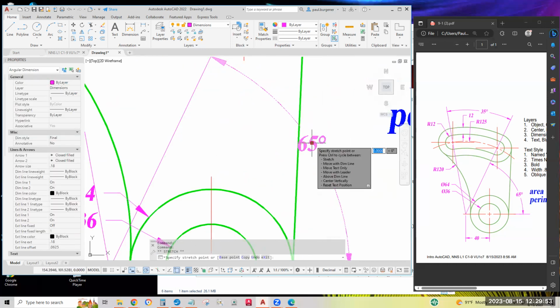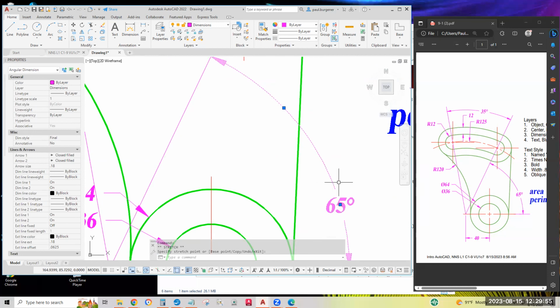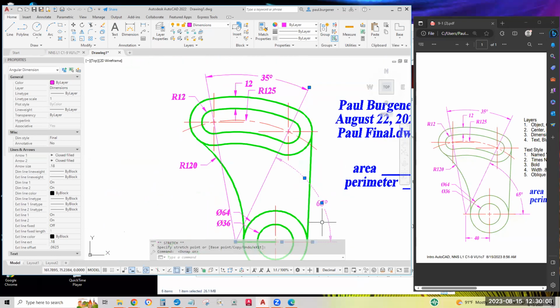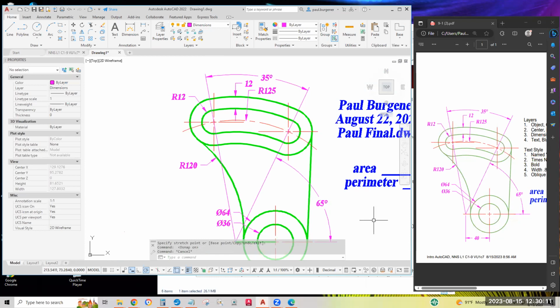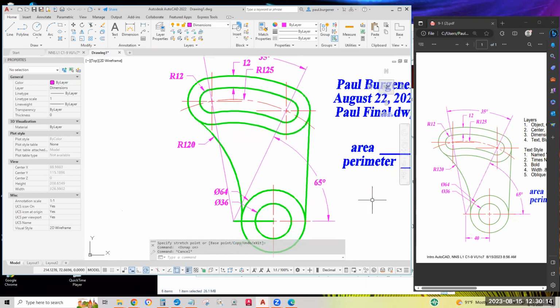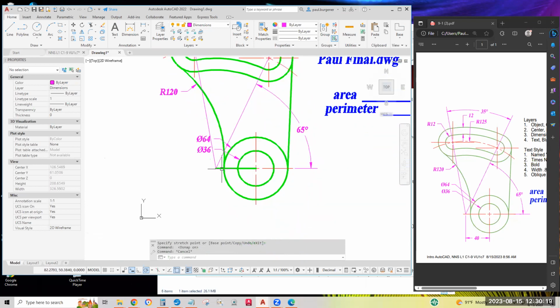I'll select the text and slide them down, not quite that far. All right, I'm going to turn off the O snap, set it right about there. Turn back on the running O snaps. F3 is another way to turn on and off the O snaps. All that's left is that 40 unit. Smart dimensioning endpoint. Endpoint, come on down. There.